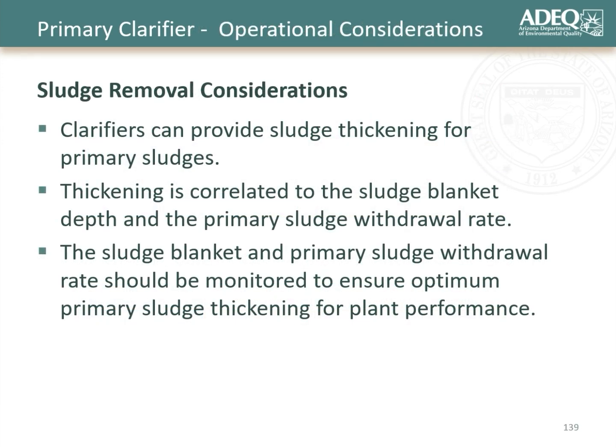So one thing we're going to talk about operationally is your sludge removal considerations. As we mentioned before, clarifiers can be used both for thickening as well as for sludge storage. So that's something to consider: they have that dual function in terms of, number one, capturing the solids, but also doing some potential thickening associated with it.